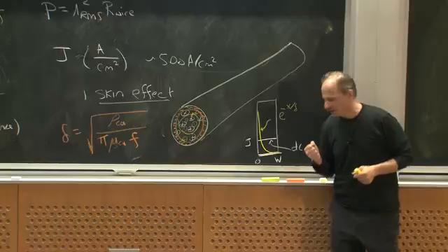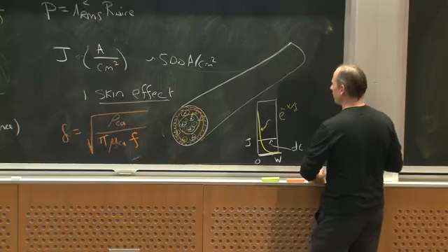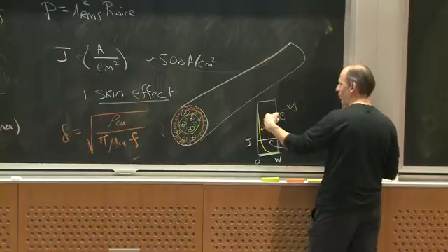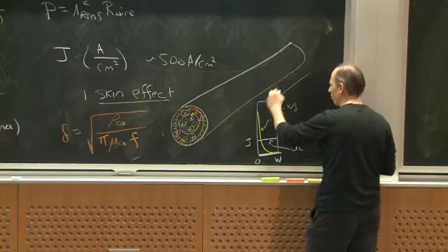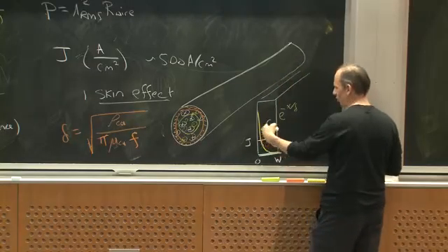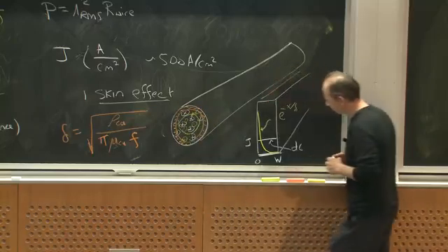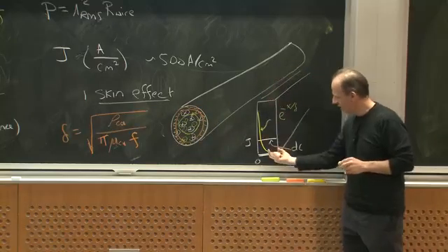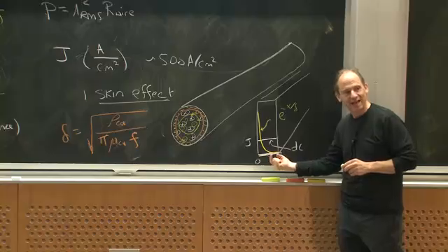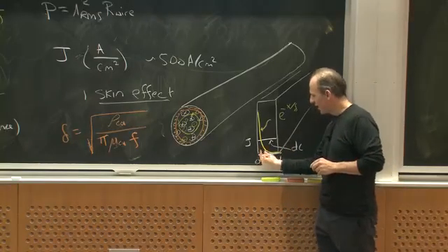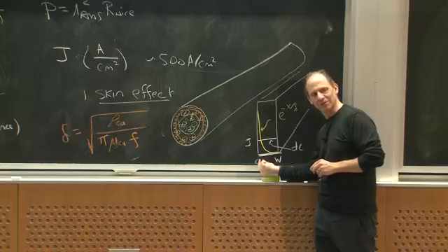Interestingly, if you have a case where the width of the wire, I'm having a foil where I'm carrying current into the board now, right? So this is a foil going into the board. Or you can do something similar here. Interestingly, the loss is exactly the same in this case as if I carried all the current in one skin depth.